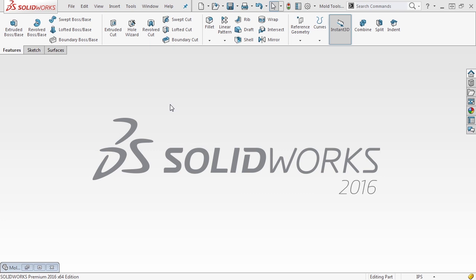So the design intent is really what the part needs to do, what it needs to hold, what its function is, and so on. And the reason the design intent is important, not only from a design aspect and figuring out how pieces move and work and so on, but it also helps you plan things like wall thickness that you need, or material selection, or whatever the end application is. Things like that really go a long way because if your end application is a part that sits outside or sits in the sun or the weather, it's going to be a very drastic difference in terms of wall thickness and construction and draft angle and just the overall quality of the part, as opposed to something that's going to be very small, very consumer, handheld based, and so on.